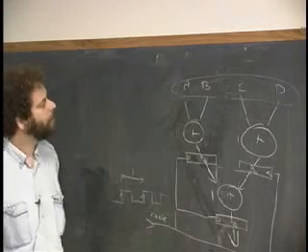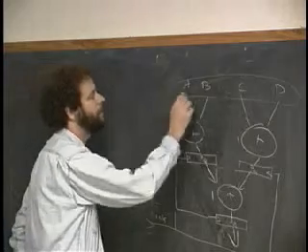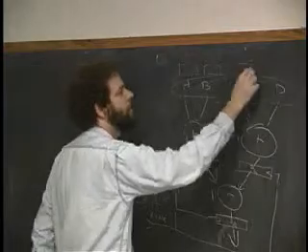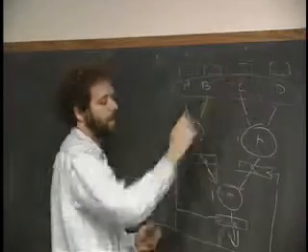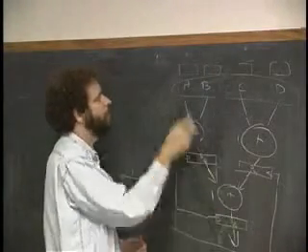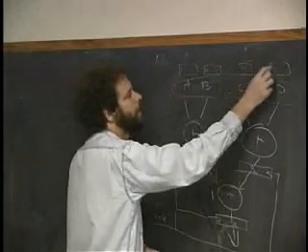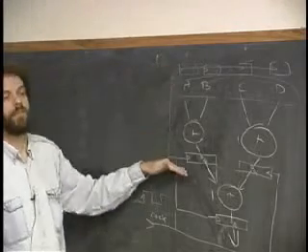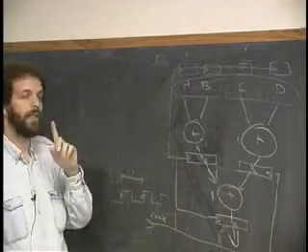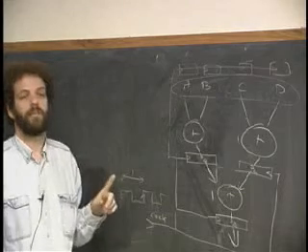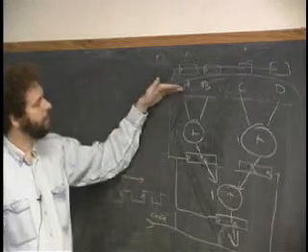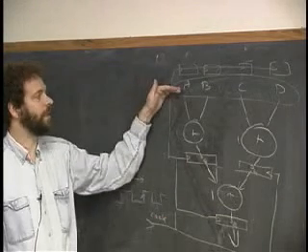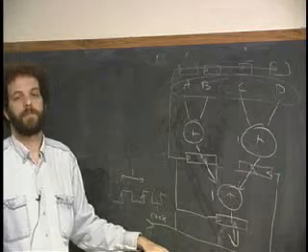In this case, it's 1 TPD of an individual unit, which in this case I've said to be 1. And furthermore, if I present the data here, if this data itself is coming from a bunch of registers, which I assume it is, I assume that the circuit that precedes this is pipelined as well. In other words, it ends with a register. Then I know that these are all being clocked by the same clock as this thing here. Then that's going to work also. Okay? But what isn't going to be true is that the latency is going to get any better. It still will take a latency of 2 units of time in order to get a set of data values from here to the end. Okay?